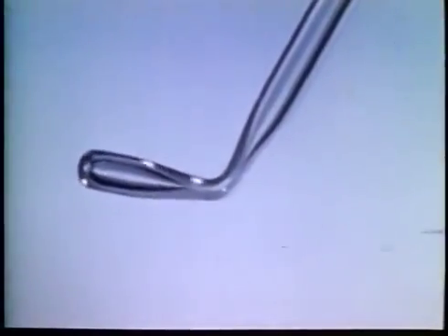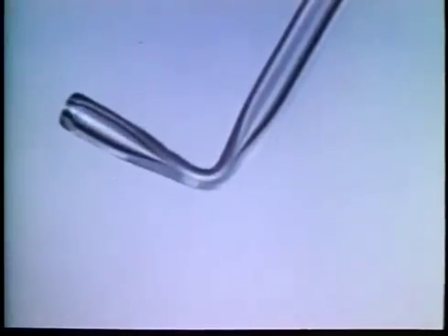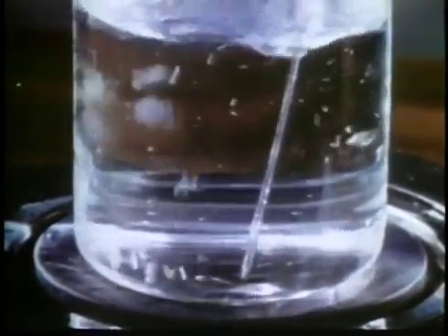If we pinch a small glass tube to create a gas-filled cavity, and then bring this rod down into the layer of superheated water, we find that it acts as a nucleation site, that it can generate any number of new bubbles. The vapor cavity never completely disappears. A small amount always remains ready to act as a new nucleation site.